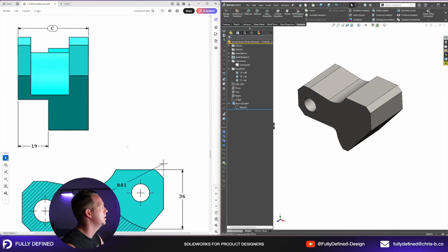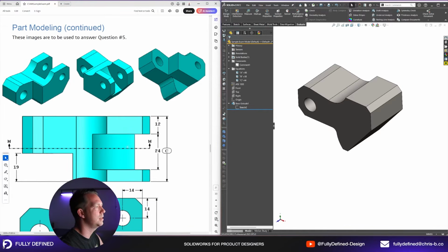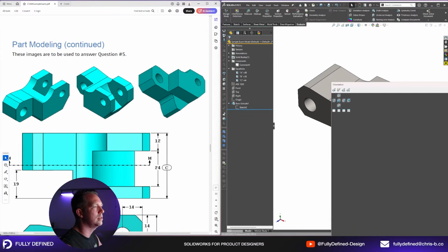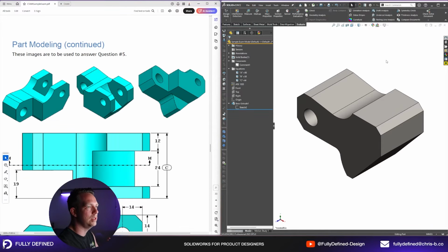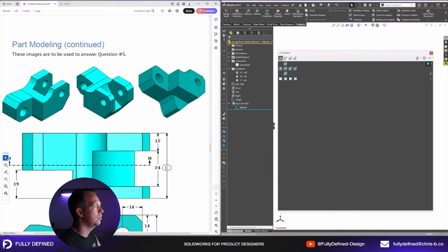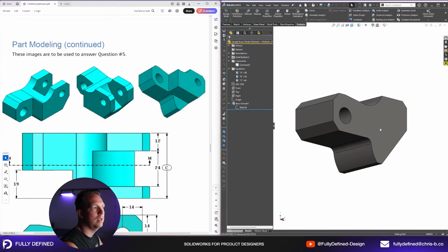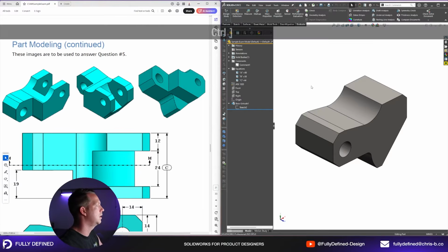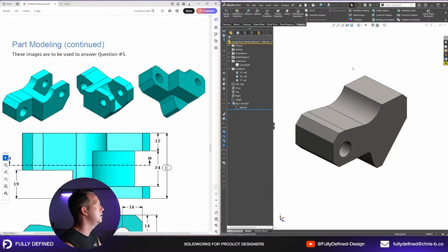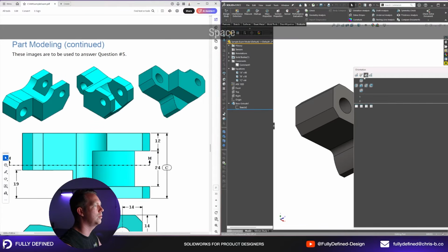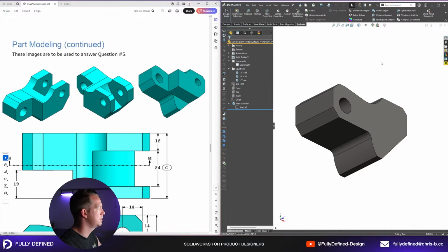Now, let's change the geometry. So, my recommendation here, have a look at the standard views and see what matches the views that you're given in that drawing. Now, this view is view number 2. If I want to save this view, I can hit spacebar and press new view and just put in 2. Now, this one to the left, it's about this angle here. I just did that by hitting some arrow keys. All right, this could be view number 1, and then this could be view number 3. We can ignore the color difference. There's nothing to worry about there.